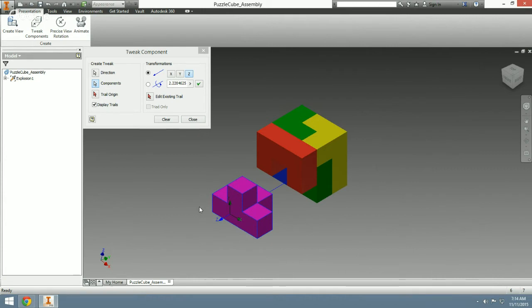What you don't want to do is move these way far away, because then they're not going to fit on our drawing file page. So right about here is good. I'm going to right click and go Apply, and then click Clear, so it no longer has this part highlighted. Those are very important: right click, Apply, and then hit the Clear button.